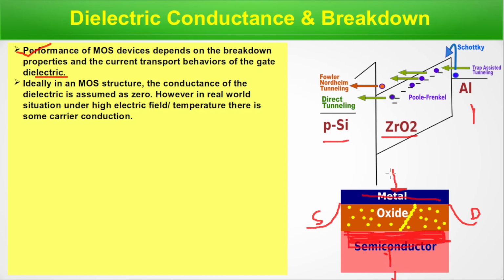When voltage is applied on this gate compared to the ground, electron concentration increases here. It also behaves like a conducting plate. So between these two conducting plates, there is an oxide. It will work best when there is zero current through this oxide. Once this channel is formed, we give a set of voltage between the source and drain so that there is a continuous conducting path. Electrons flow from here to there.